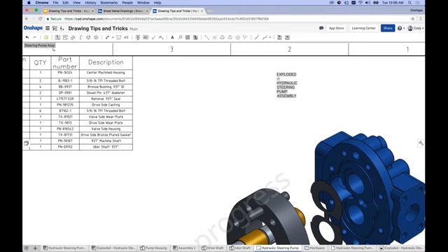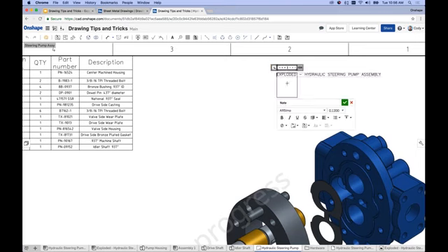That's what I was asking about. Set a property and then go back to try to determine what was selected. If you mouse over it, you should see a flyout that says the property name. So I've edited the note. I double click the note, mouse over it, and it says sheet reference name.